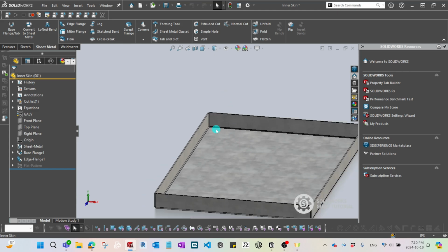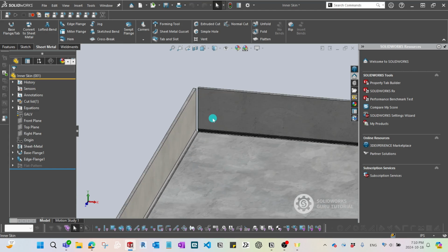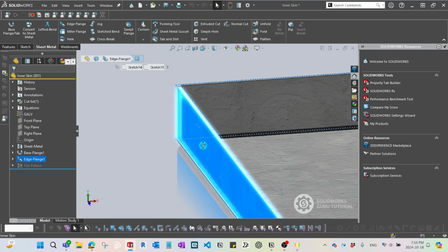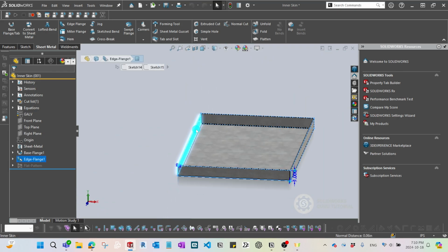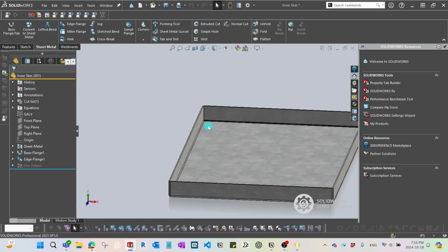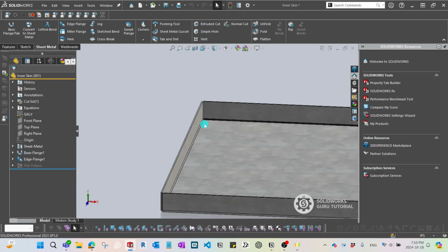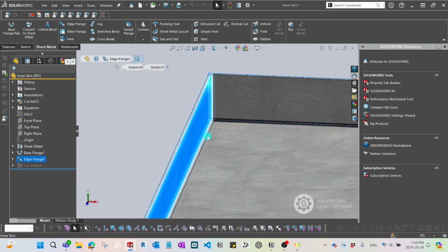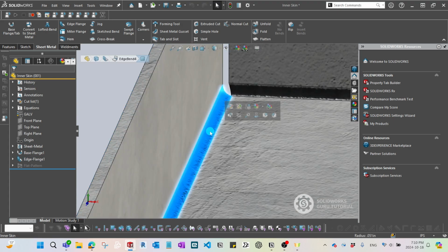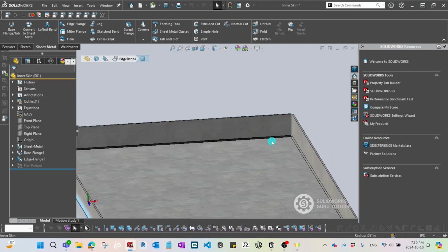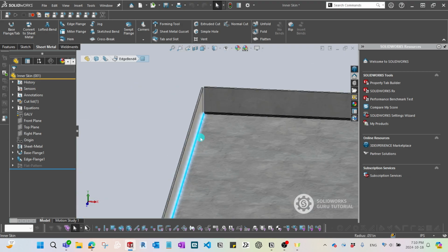But this time it's just what we should exclude from the equation. If you think about it, we have to know the thickness first, because this panel is going to be going underneath at each end. So you have to think about subtracting the thickness on one side, and also subtracting the bend radius, and then one more time. So it's going to be 2 times the one thickness and the one bend radius.